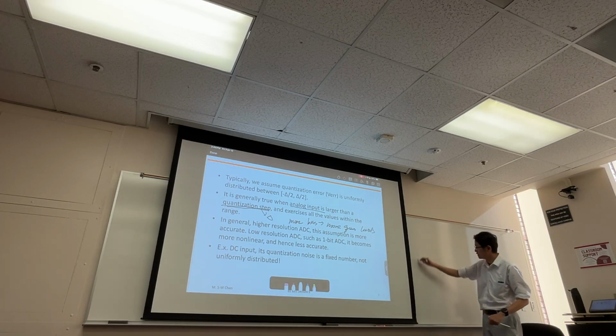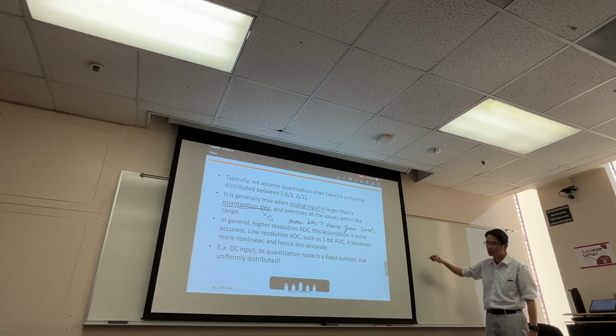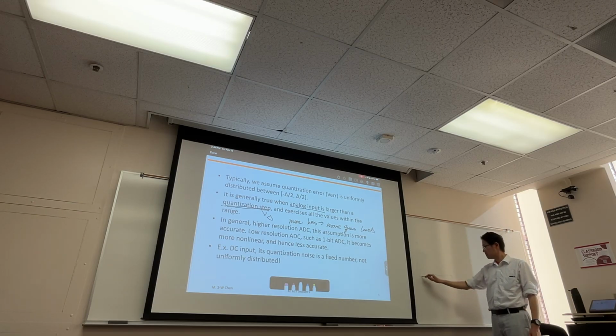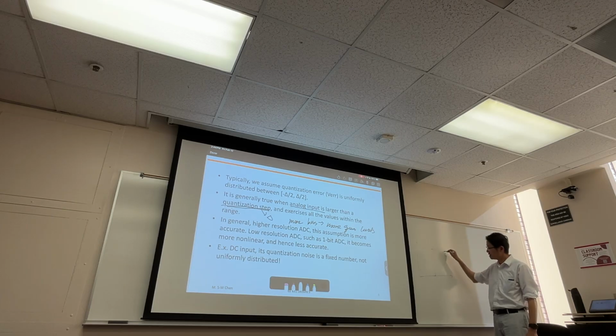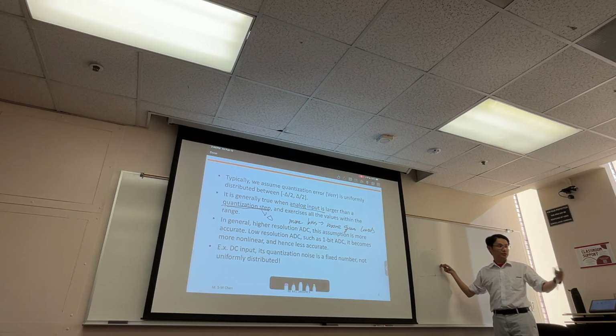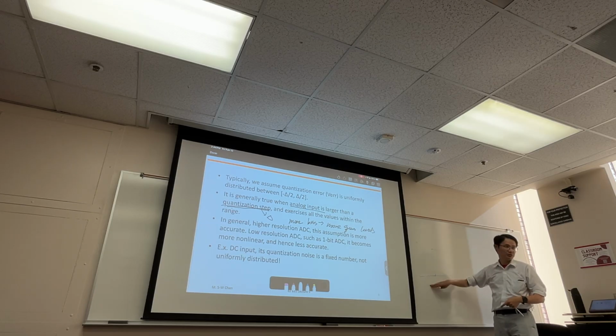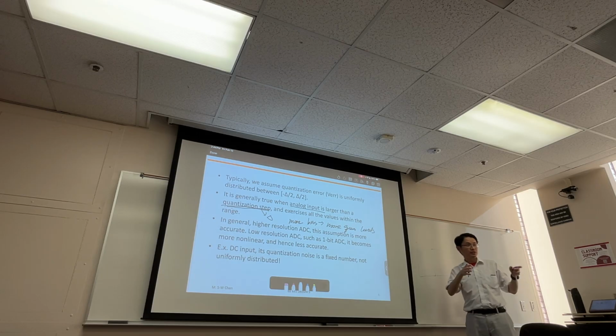How do I draw the transfer function? If I do a 1-bit ADC, do I have a staircase? Like this. This is also called a comparator. You just compare a value: is it 1 or 0? So in the future, if you see a comparator, you can call it a 1-bit ADC, that's okay.